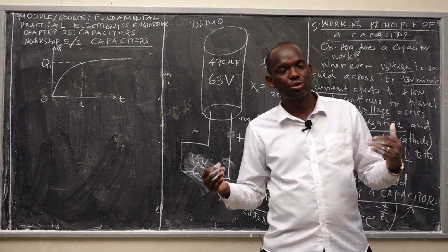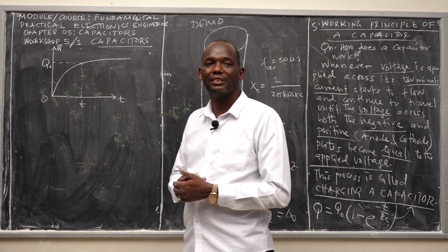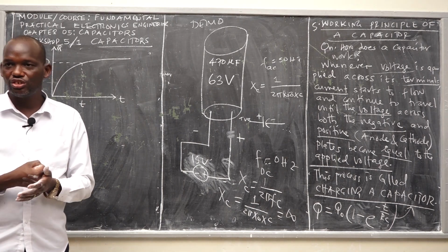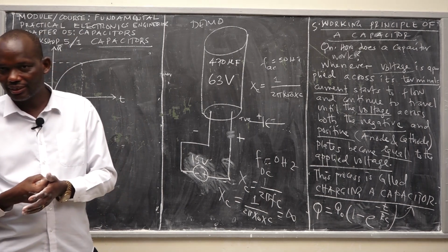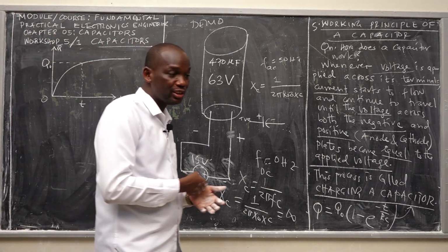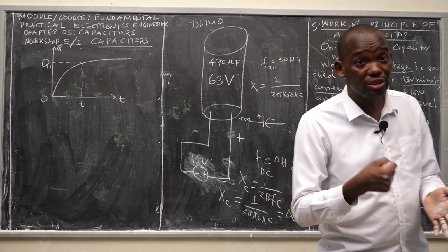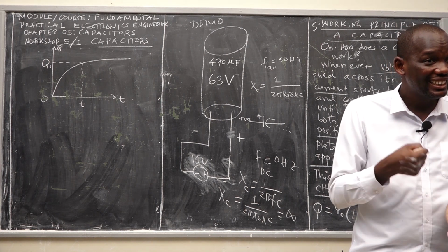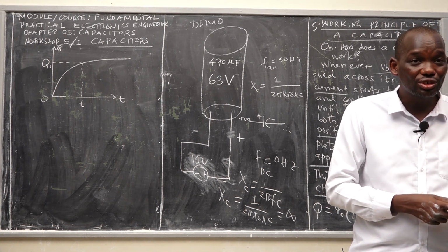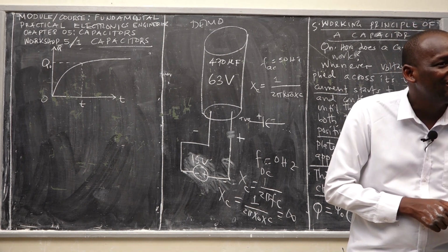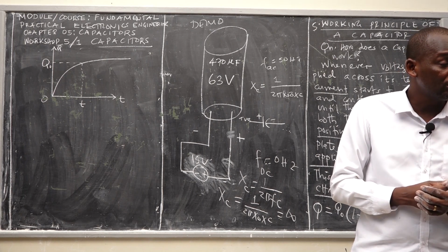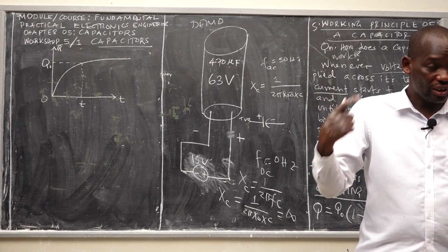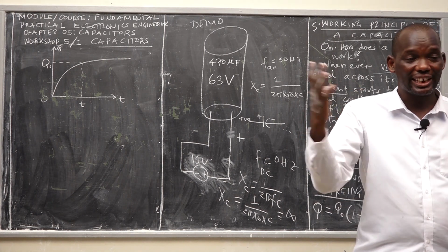Then we come to another phenomenon that's called discharging. Say discharging the capacitor. Discharging of the capacitor is actually using the electric charge or the electric energy stored within the capacitor, right? How does the capacitor discharge? It's simple. You just connect the capacitor with the load, and then the capacitor discharges to cause the flow of electric current. The discharging also takes a short time, but depends on the capacitance of the capacitor, and also on the amount of current that the load draws. If the load draws a small amount of current, yes, the capacitor can discharge even within an hour.